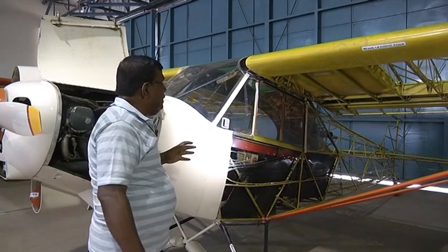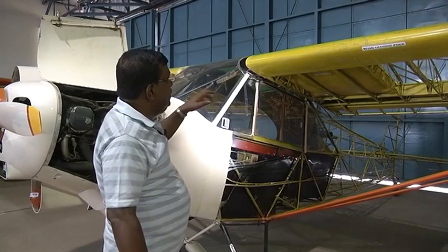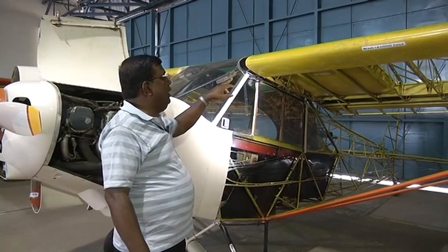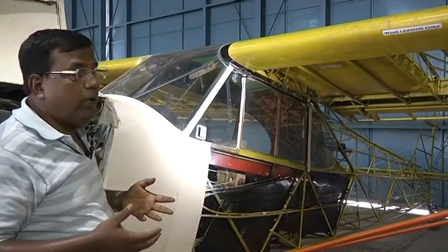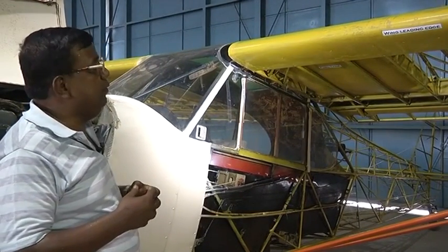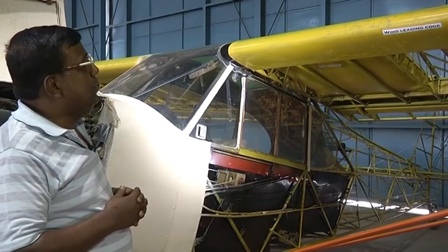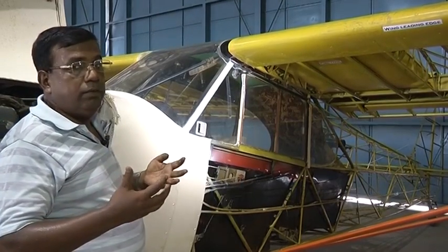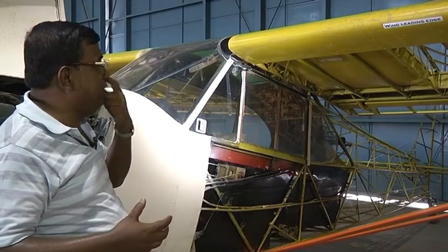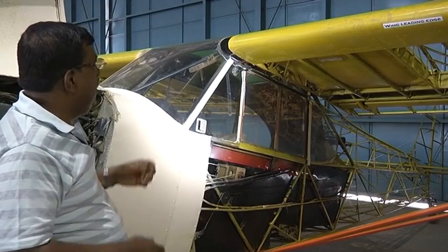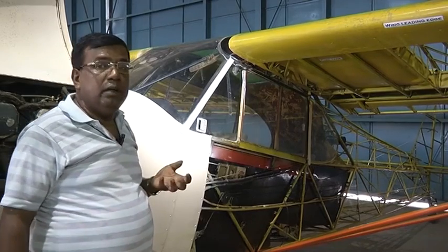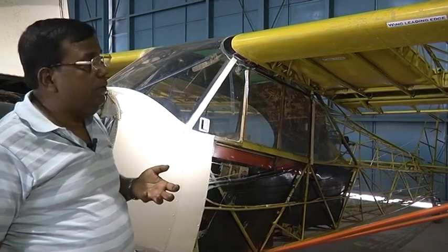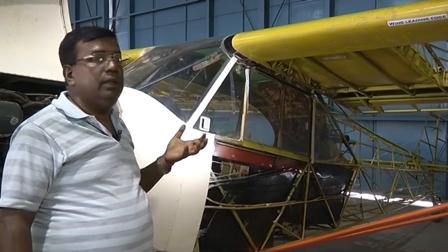So the most important thing we should understand is that we need to cater some space for fuel. The moment I put in a fuel tank, not only is the weight of the fuel important, but it is also important that the fuel tank is leak proof and its weight is not very high, otherwise it will change the wing loading. Also we need to know which fuel pump I'll be using, and the reliability of the fuel pump is extremely important for good performance of an airplane.